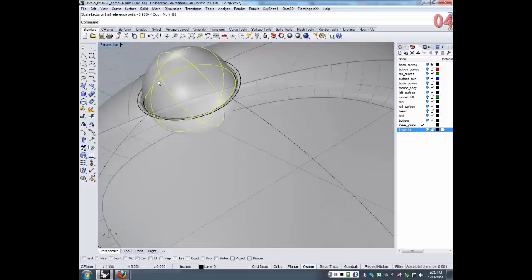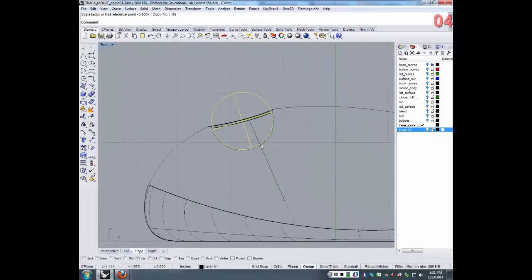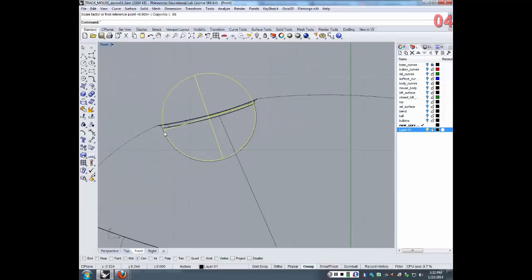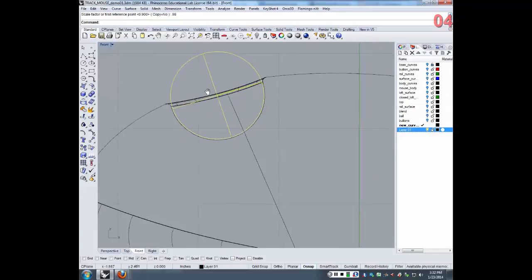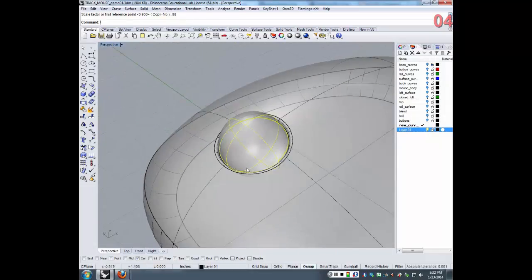And that's just enough so that if I were 3D printing it, it would provide enough space to get some support material up in there. Do you follow? Just offset it just a little bit. This is still below that hemispheric line right there, so it would lock it in, and it would roll around inside of there. Okay? So you follow that? And that's sort of the technique that you use to do balls and buttons. You carve out your surface, boolean it back, and then you insert the object that you want to add.